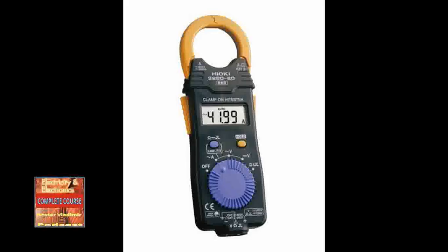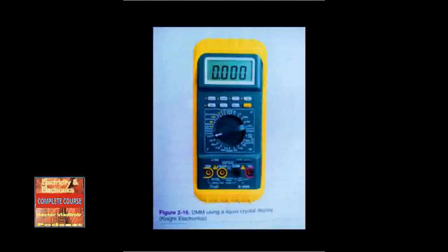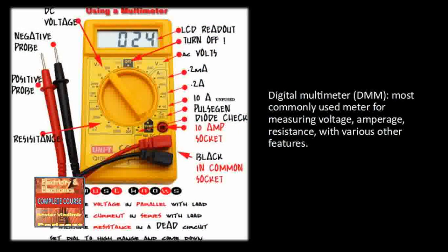This is a formula used to equate AC voltage to DC voltage. The RMS value is the equivalent DC value of an AC waveform. Many meter scales and some DMMs use this abbreviation. Some meters have a special location to plug in the meter lead when reading AC voltage or current. Many meters have a scale marking printed as RMS. This simply means that the readings taken on that scale are equal for DC or AC voltages.